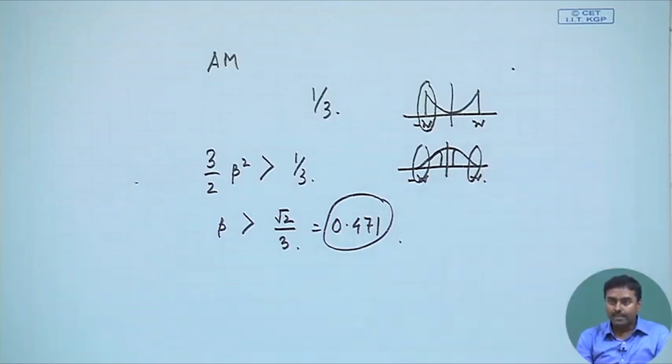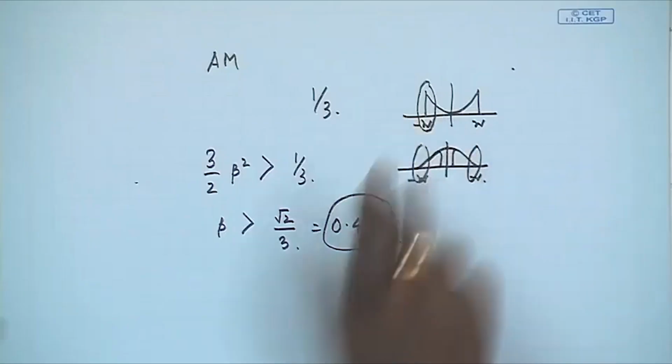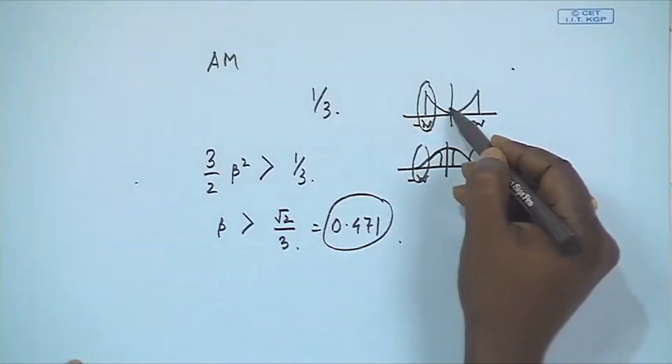So, to combat that, we can do some pre-processing at the signal level. We can boost the higher frequency components of the signal compared to the lower frequency components, because lower frequency components are much better off in terms of noise, as they are getting added with a lesser amount of noise, whereas the higher frequency components are getting more noise. So, if we boost them a little bit, what will happen?